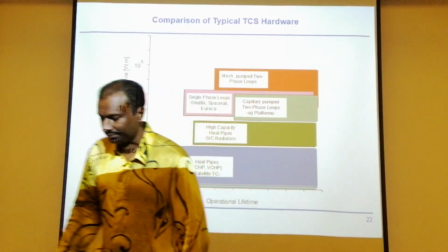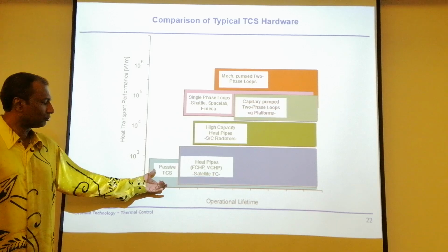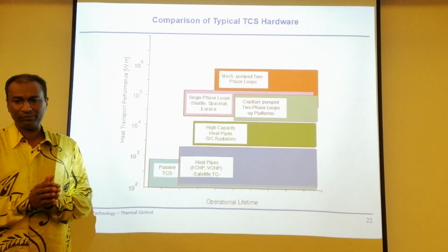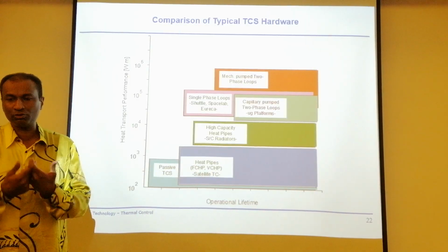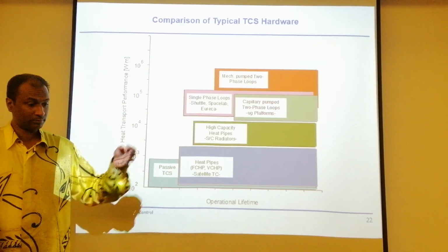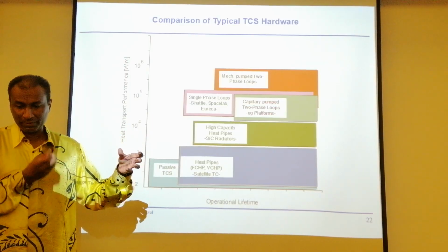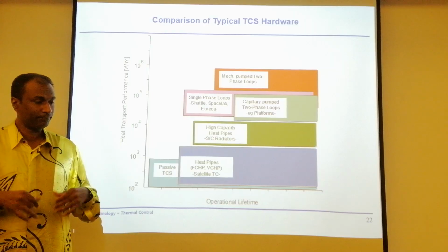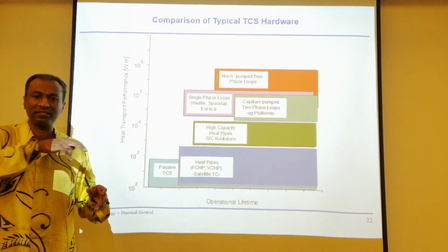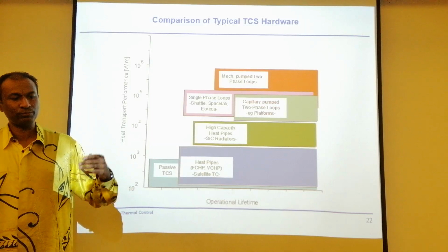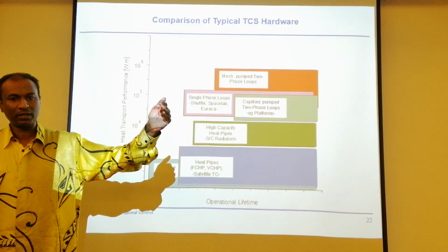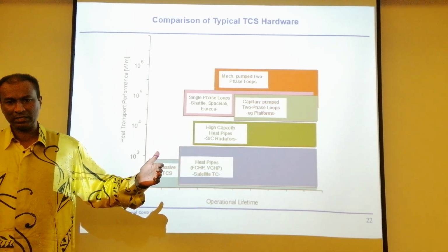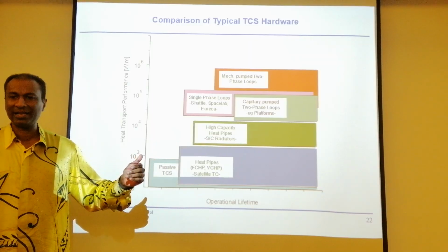Another one, passive control system. Passive thermal control system, practically, you have a heat pipe. If you have a heat pipe and you don't fix a pump to it, the flow is still going to happen because there is heat, and because of the capillary effect in the heat pipe and the surface, together with the surface tension of the liquid, you are going to have a very passive flow. Remember, heat is going to flow from a hot spot to a colder spot. That's how heat works. So that transportation works without electricity.